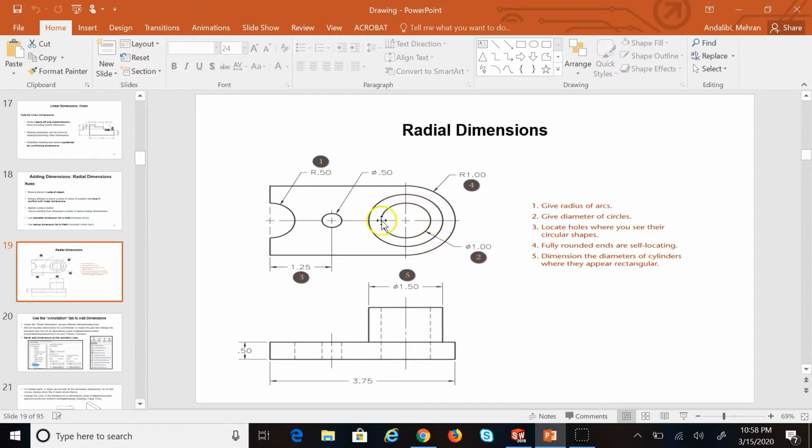And then I have the inner circle, which is the cut extrude, again shown with a rectangle but with dash lines. So the diameter of the extrude is shown in the front view, but the diameter of the cut extrude hole is shown on the top view. You might wonder, couldn't we show both of these diameters on the front view or both of them on the top view?